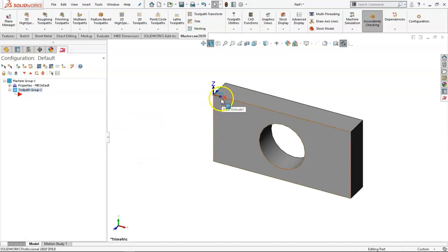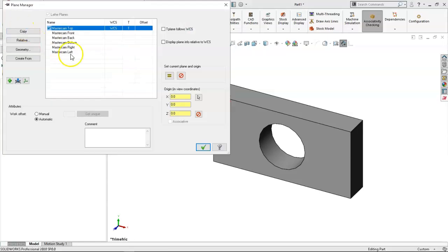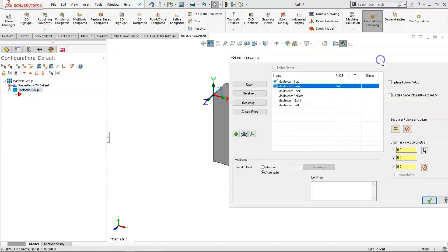So like I was saying, one of the first things I want to observe is where exactly the X, Y, and Z are for the CAM, because if it doesn't follow the Solidworks triad, then we're going to have to make that adjustment. So that would be one of the first things I want to check, under the planes. We'll need to establish a new one, or let's see, if we go into the front, WCS and tool, then now I have the correct orientation for this part.